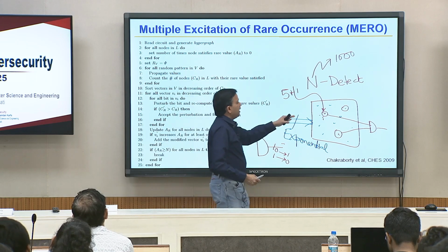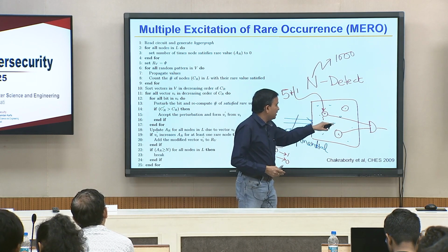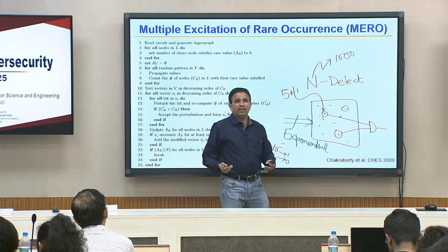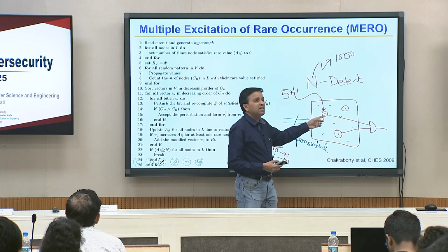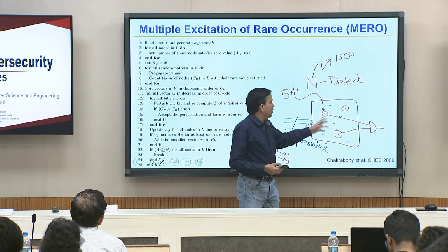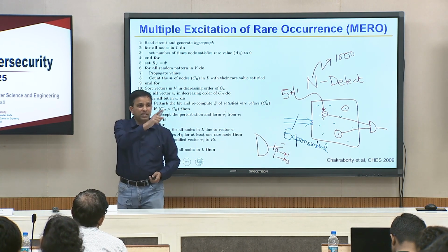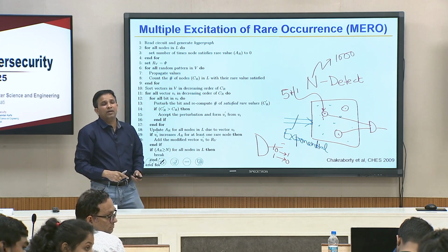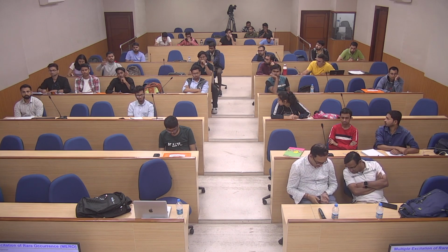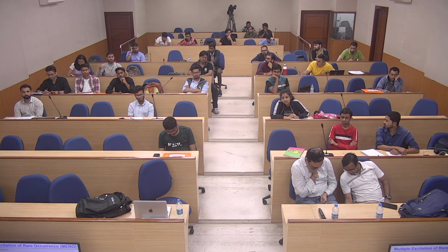So, n-detect relies on the principle that you are trying to activate only the rare ones, you do not care about the other folks, because that is not what the trigger is created with. Second, when I am activating this n times, there is a high likelihood these two or maybe these three together would be activated at the same time. So one trigger can trigger other ones? May. Okay. Statistical likelihood. That is why this is called statistical testing.